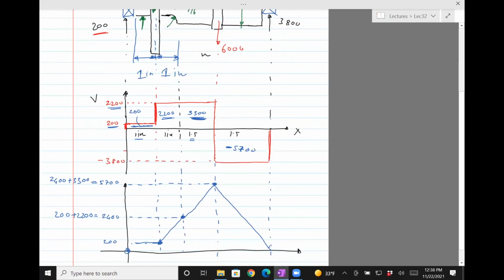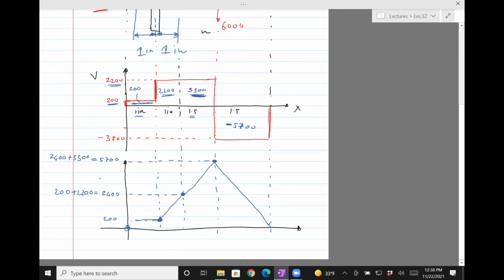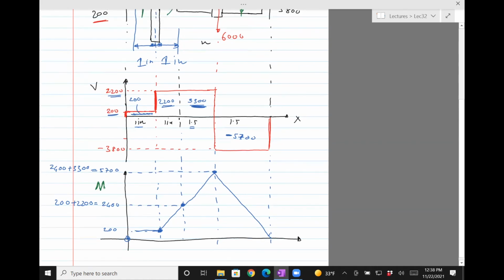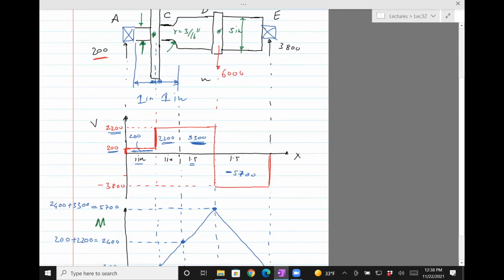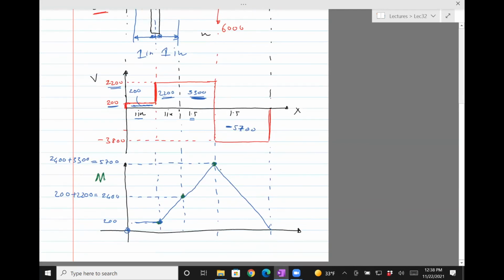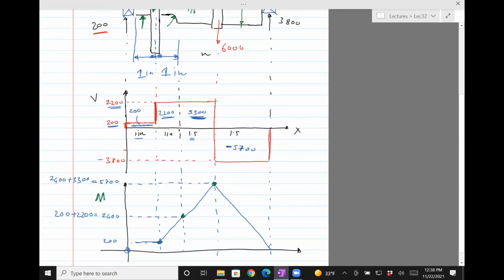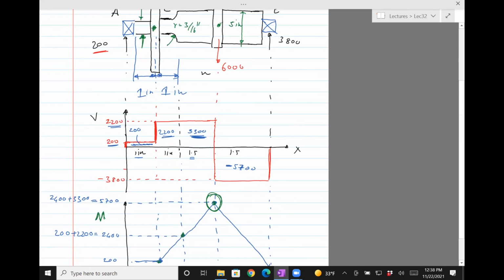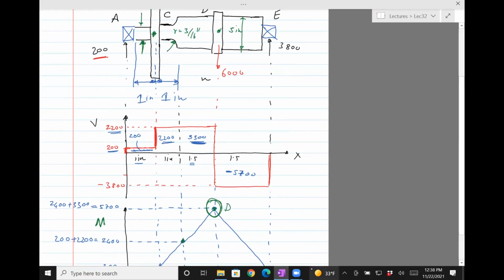We only need to look at the bending moment equation, or say the bending moment diagram. Okay, the stresses are low here. So again, I need to focus from here to here. So the stresses are low here, become high here, and become maximum here. It seems like the stresses are the maximum over here. So that might be a point to consider for computing the factor of safety.